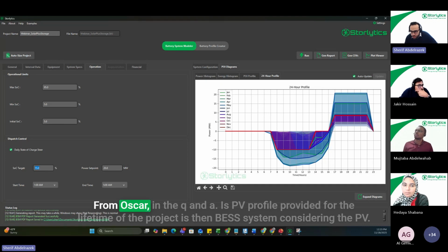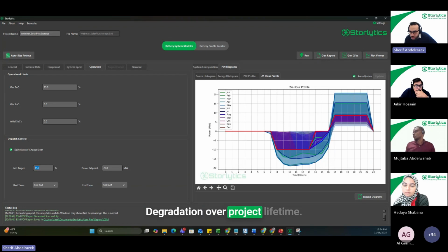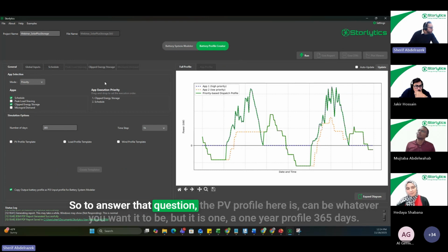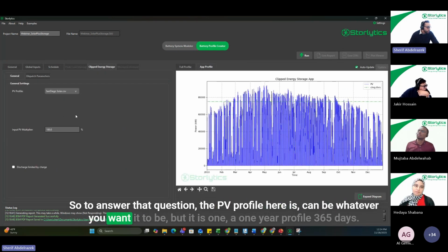Right, from Oscar in the Q&A: is the PV profile provided for the lifetime of the project? Is the BESS system considering the PV degradation over project lifetime? To answer that question, the PV profile here can be whatever you want it to be, but it is a 1 year profile, 365 days.